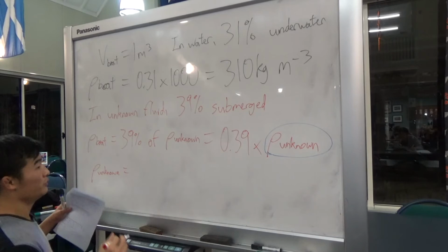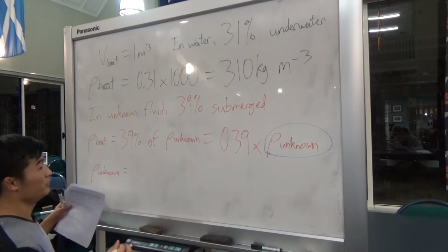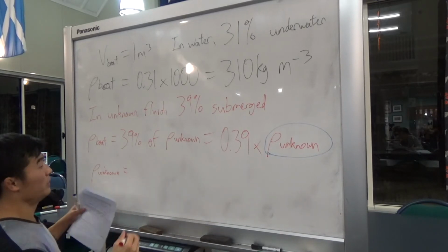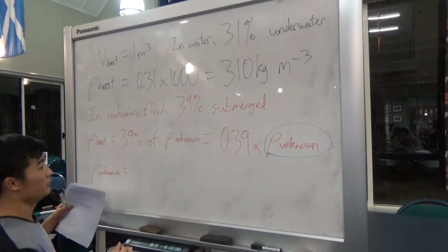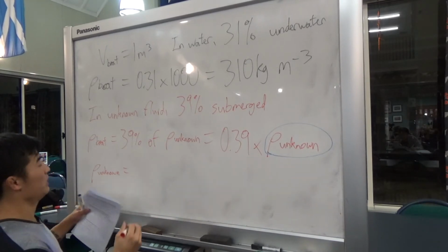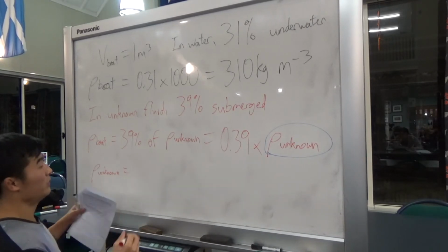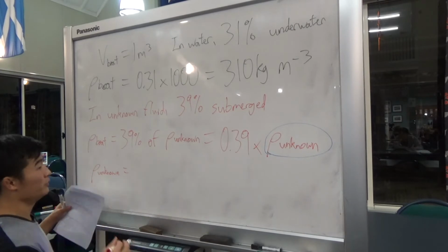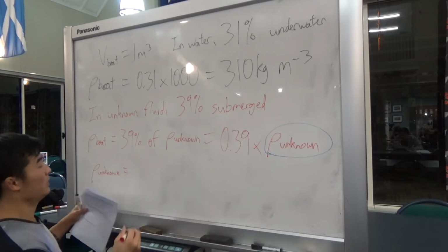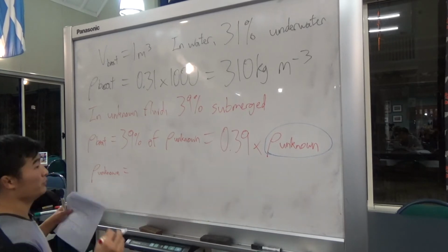And if the cross-sectional area is 1/4, the velocity at point 2 will be 4 times greater. So V2 will be 4 times 0.02, which is 0.08 meters per second. Okay, so we figured out the velocity at point 2. So we actually didn't need that for question 8. We need that for question 9. So now we'll focus on question 9.